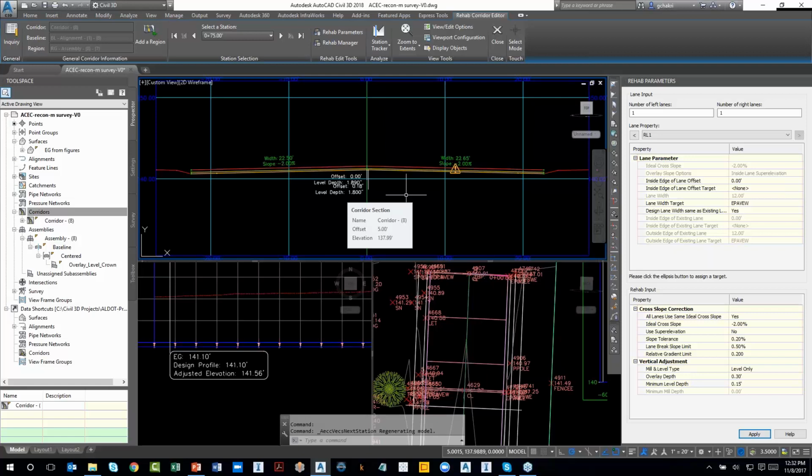Exactly. At this point, this is no different from any existing corridor object. If I close this and select that particular corridor, go to my existing corridor cross-section view and plot the cross-sections, these parameters are applied there, and you can see that in the CSV or in assembly properties, or whichever way you work in your current procedure. The same things apply, and all this information is applied to that section-by-section corridor also. Great, thanks for confirming that.